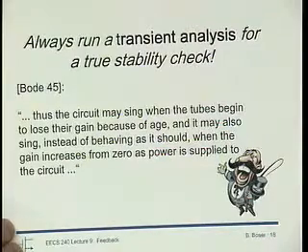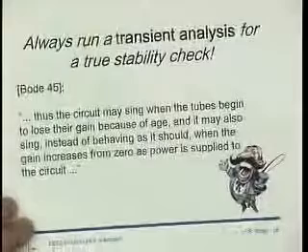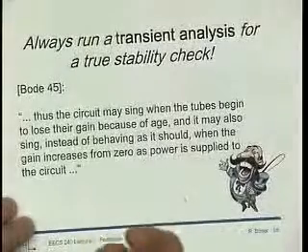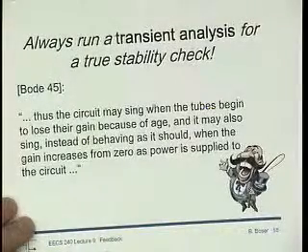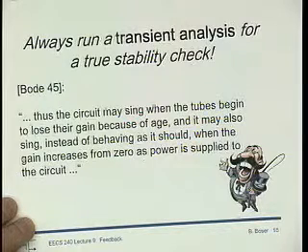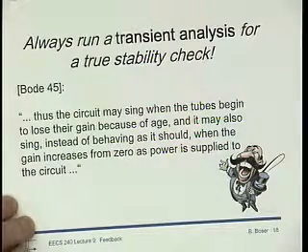For example, many circuits have a startup circuit, right? We've talked about those. So they work fine if the power goes from 0 to VDD. But many of them actually fail if the power goes from 0 to VDD, back down to VDD over 2, and then back up to VDD. Right? So you got to look at such things. If you tape out a chip, then you want to know all of this.